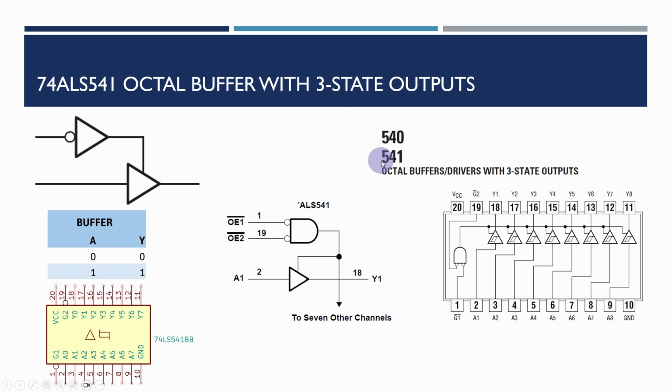Now, the advanced LS series is what we've been using in a lot of these projects, mainly just because it has slightly higher output capabilities and can switch a bit faster, particularly when we're starting to look at using these chips in video controllers and things. Then they're just able to handle the higher frequencies a bit better.